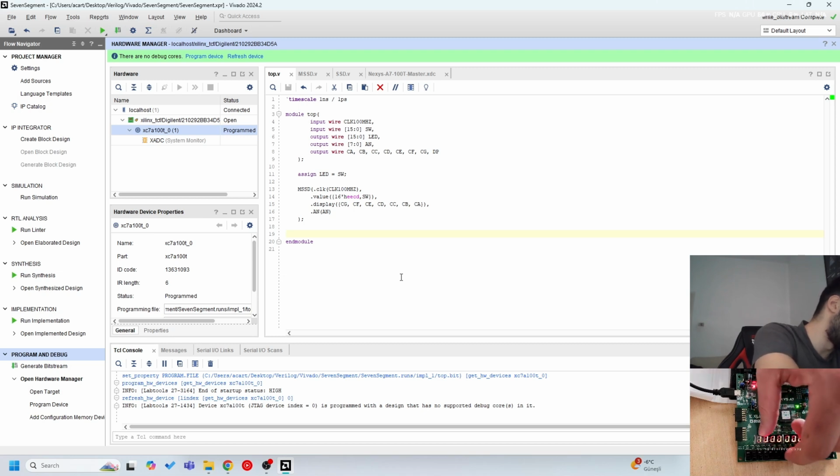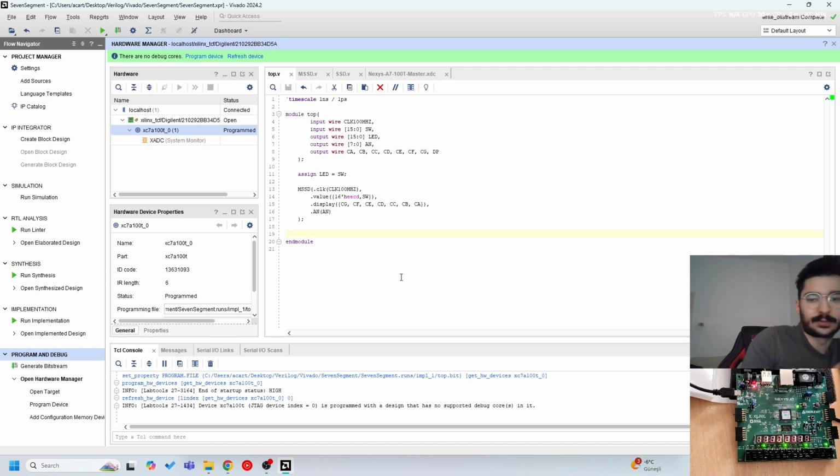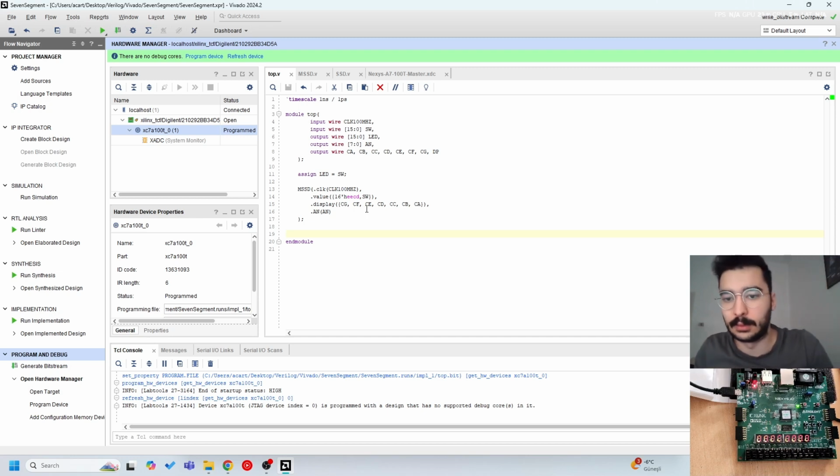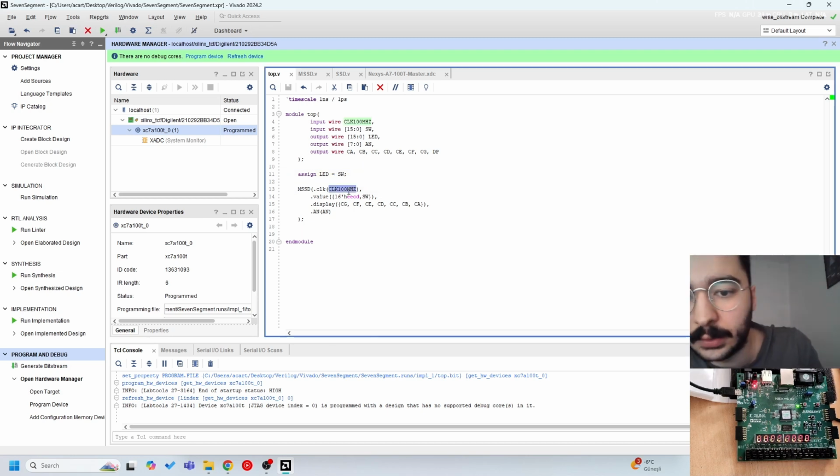And if I select all of these digits to 1, like the first 4 of them, you can see 1, but it's not clean. There are still faints of others because we have other digits, EECD, that the module wants to display, but it cannot switch these ports at these high frequencies. Now, the only way we can fix this issue is to reduce our clock.